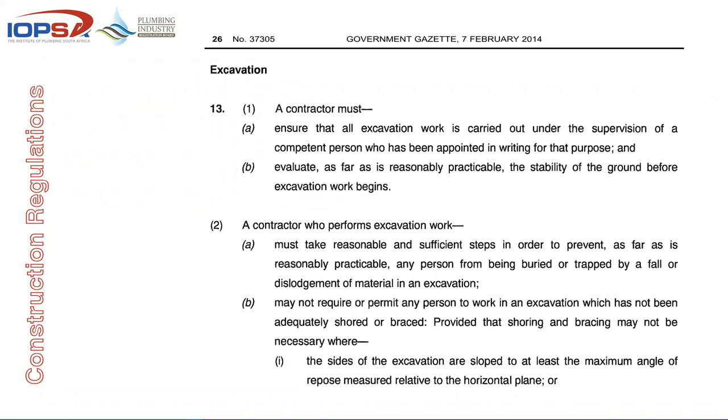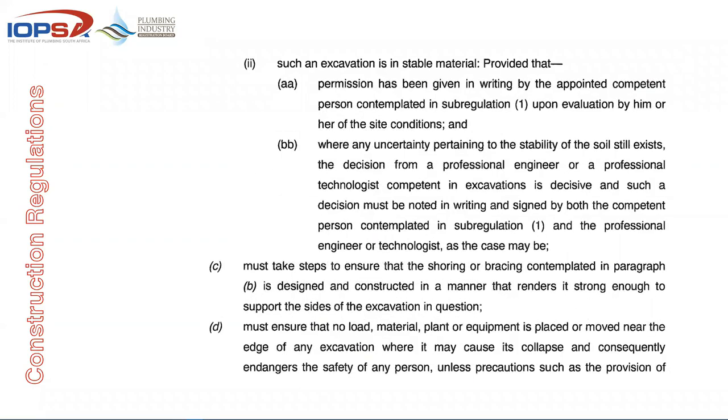far as reasonably practicable, any person from being buried or trapped by a fall or dislodgement of material in an excavation. He may not require any person to work in an excavation which has not been adequately shored or braced, provided that shoring and bracing may not be necessary where the sides have been sloped. It's a very practical document. It's not unreasonable requirements.